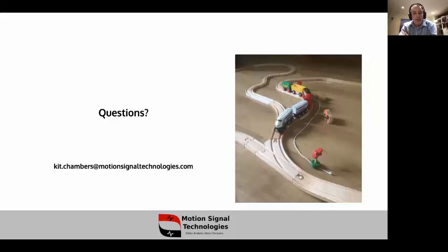And the other really big advantage for it as well, which is not necessarily realized by just picking vehicles, actually comes from doing a lot more detailed analysis of the data, because the actual data that you're receiving on that DAS fiber is not just the vehicle, it's actually propagated through the subsurface. So there is information on the subsurface, and cameras can see the top of the road, but they don't necessarily see the underneath of it. So there's strengths and weaknesses in there.